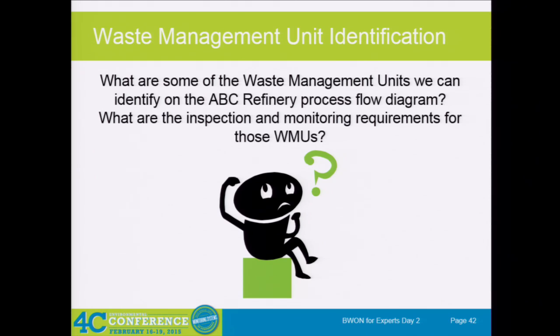This is true. Okay, so 1V1 is our benzene stripper. And what kind of a waste management unit type is that? It's a treatment process. So for 2BQ, you would treat it as that. For 6BQ, you'd likely just call it another waste management unit. It's a fixed roof tank is what it looks most like. And those require what type of inspection and monitoring? Quarterly visual and annual NDE. Right, so both of those.